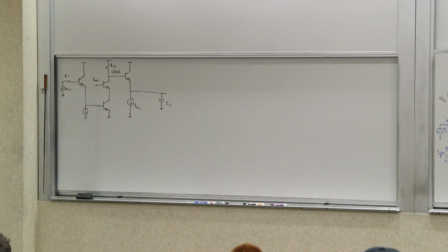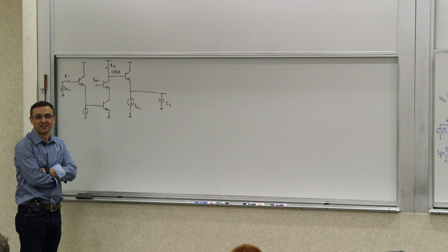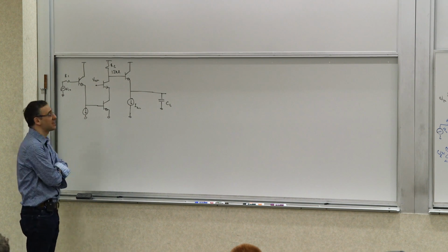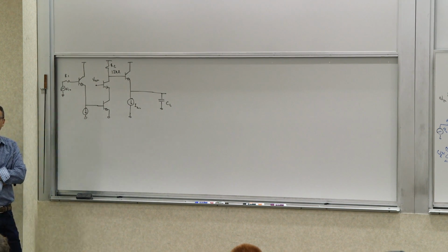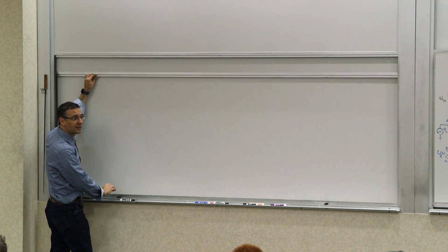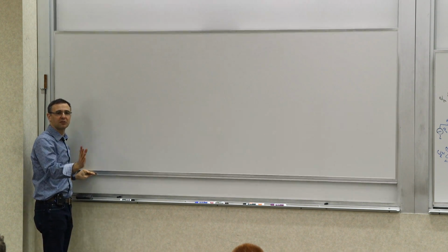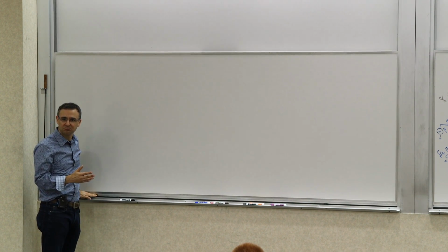Now, transistors are more expensive than capacitors and inductors in discrete designs, right? So you don't want to add a whole bunch of transistors. You want to basically stick with these four if you don't have to add any more. So if you're turning this into a discrete design, what is it going to look like? Well, I'm going to have to bias these transistors properly, but I can use resistors and capacitors, and those things don't cost me much.